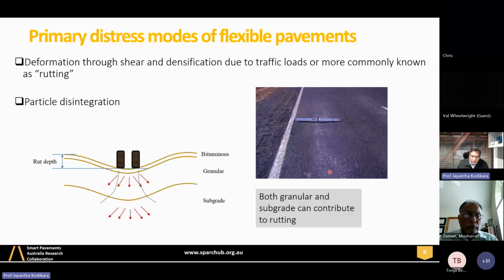There are, of course, limitations. So you need a larger mold to capture these large particles. That's why the diameter is higher, and then the height should also not be too high, because if it gets too high, you have side friction coming in quite significantly. So you need to optimize that. Therefore, we believe that this is a compromise to get a practical solution to a complex problem.